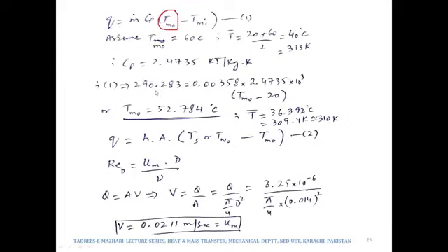So, by putting in the values of Q and mass flow rate and Cp, we will get an average temperature of 313 Kelvin, and from the same table that we have been using before to find out the properties of the fluids, we can then determine the value of Cp by interpolating. So we will get at last the value of Tm naught as 52.7 degrees Celsius. So it is close to 60, right? Someone could have assumed it as 40, so even then it would have been good enough. This is how we move forward to solve the problem.